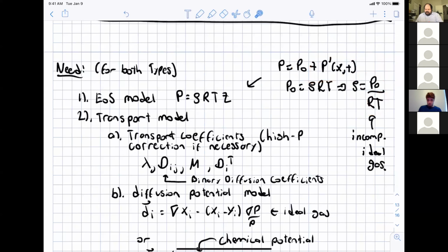Basically, you are separating the fluctuating fluid mechanical pressure from the thermodynamic pressure. But for a compressible flow, you cannot do this. So this would be for low Mach number only. Okay, and so there are all kinds of games that people who work in low Mach number combustion deal with.